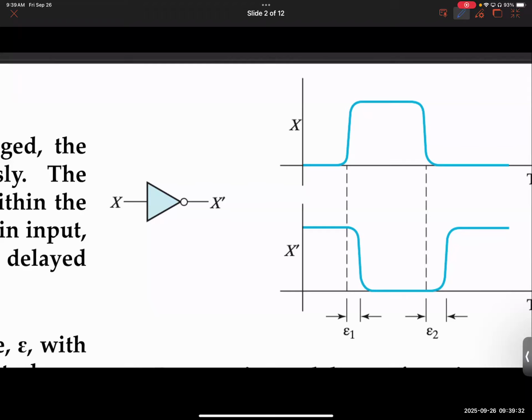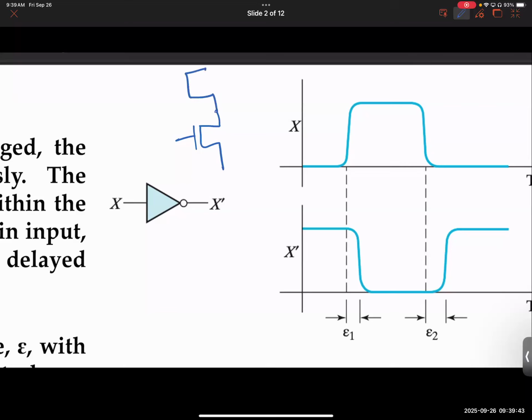So anyways, the reason is, I told you that you have a physical hardware for every component that we're using. How do you implement an inverter? You have an NMOS and you have a PMOS, and there are two types of transistors. You provide the input in the gate terminal, you get the output from its drain terminal. You don't have to know what gate and drain are for now. There are actually 4 terminals in every transistor. Gate is one of them and drain is the other one.